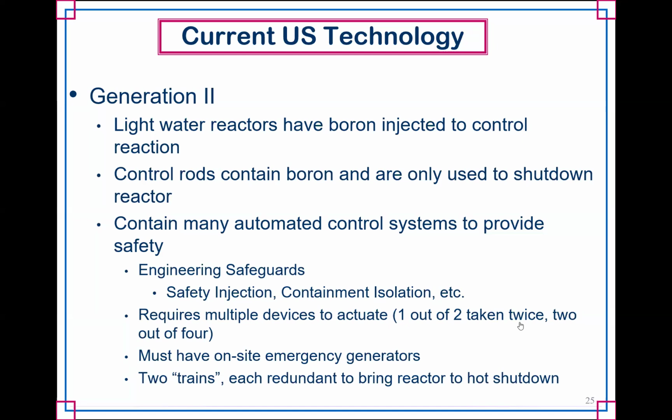So if I'm getting high radioactive levels, that means that something has broken free, and I don't know why, but I have to shut down all the air that's coming in and out of containment. So I would isolate it. You don't want these systems to operate by mistake, and so you have to have very, very high reliability.